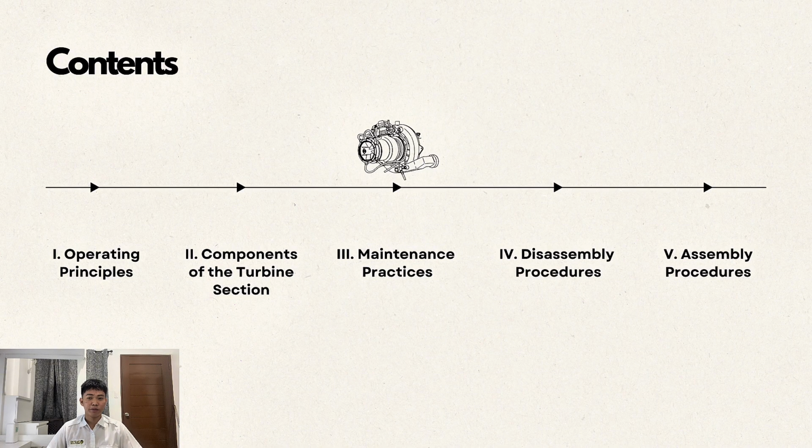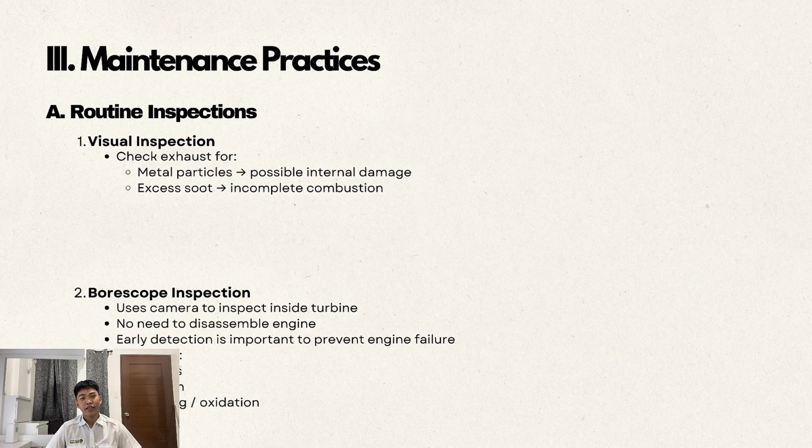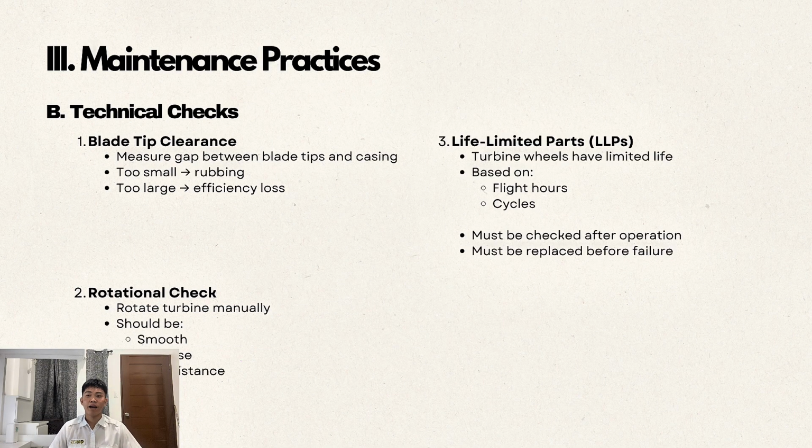After making sure to keep this in mind, let us move on. The manual emphasizes that all personnel must strictly observe warnings, cautions, and notes before performing any procedure. That is why maintenance must be performed using approved methods, tools, and materials only. The engine must be in a safe condition, shut down, and allowed to cool before work. All airframe and engine interface connections must be properly secured or disconnected when required. Failure to follow these instructions may result in damage to equipment or injury to personnel.